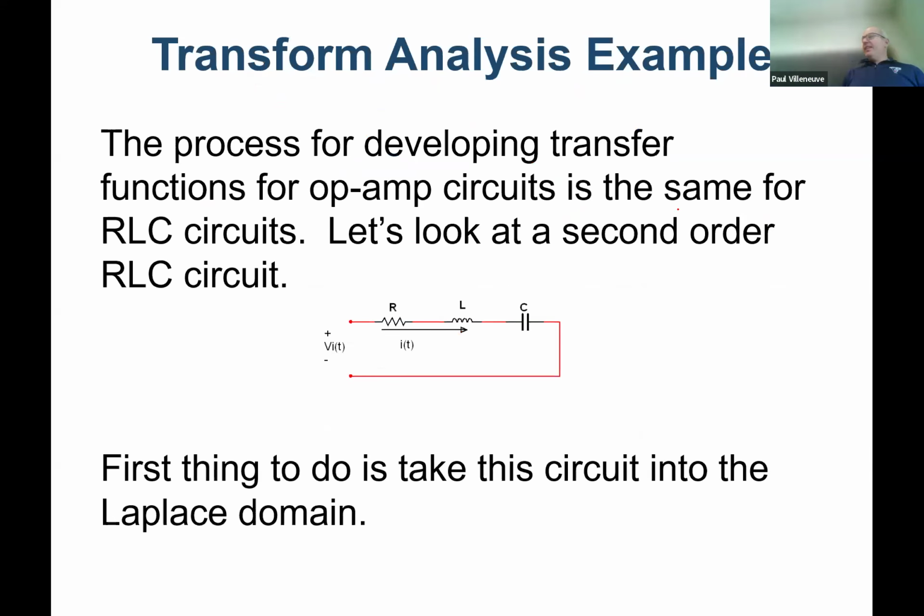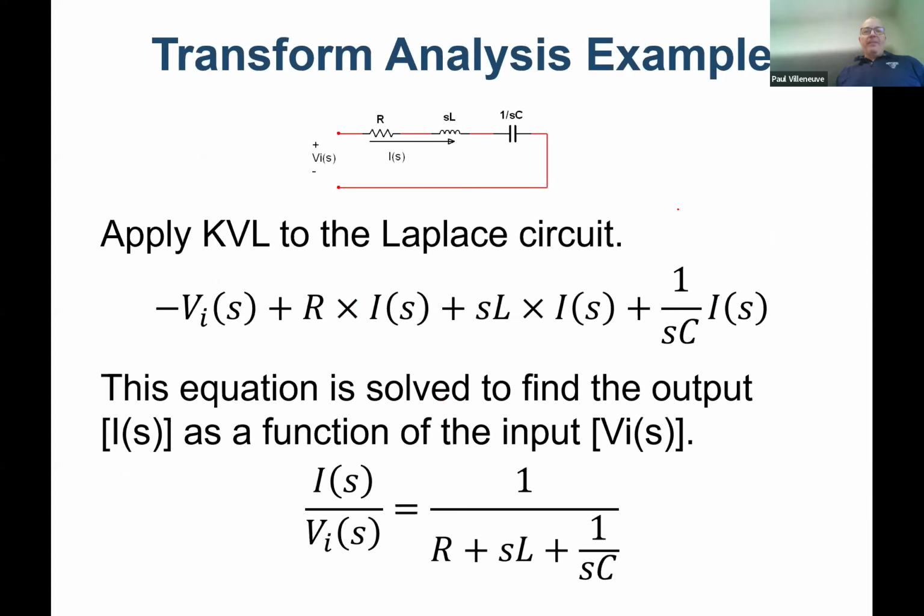All right, so now we've got op amps and hopefully a little bit of review for op amps. Let's finish up the section by doing a transform for a series RLC circuit. We can't use the y of t equations for first order circuits; we've got to use the RLC. Because we have an inductor and a capacitor, we've got to use Laplace to do this. So the very first thing we're going to do is take it to the Laplace domain, because I don't want to solve or write any differential equations. I want to make it easy on myself.